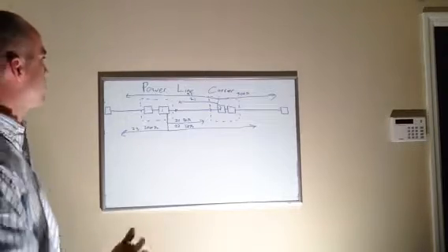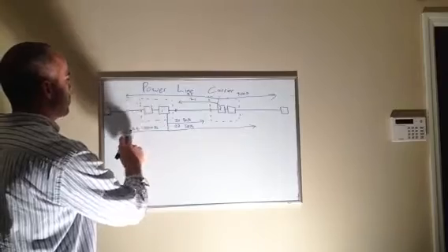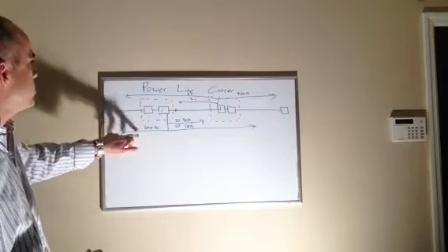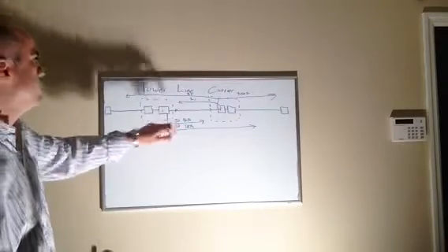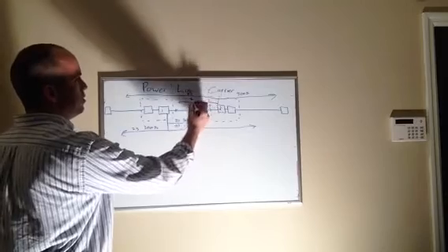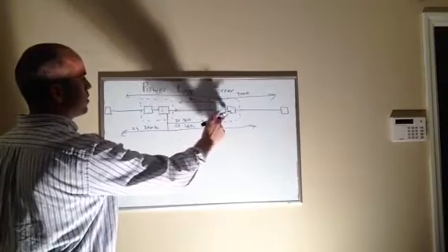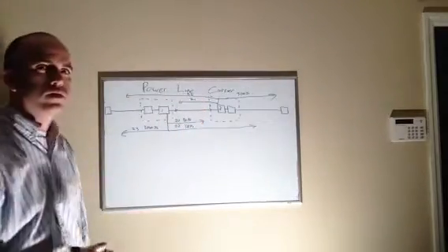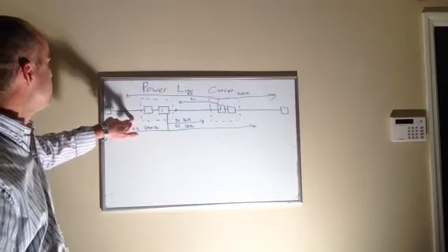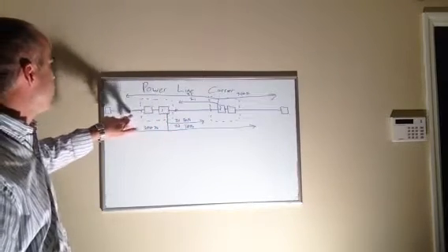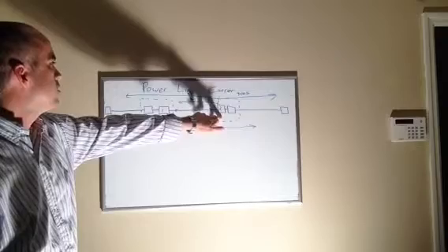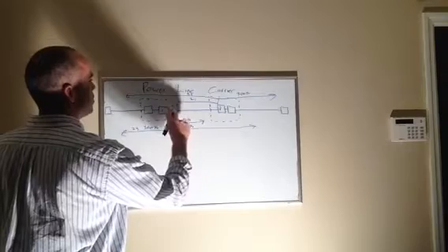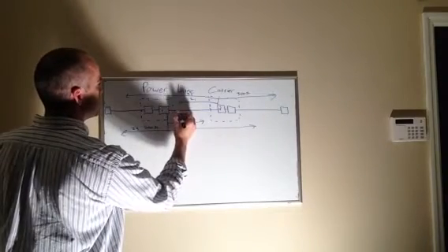So how do we accomplish this? Well, this breaker, Zone 3, is looking back. Okay, this breaker number 1, Zone 3, does not see this fault reverse looking. So it does not send carrier blocking. So because this breaker is not receiving the communication blocking signal from this breaker, it makes that Zone 2 instantaneous. Because this one does not see the fault, it does not send a blocking signal to Zone 2, which makes the Zone 2 an instantaneous trip. So you're probably thoroughly confused, so let's do this.